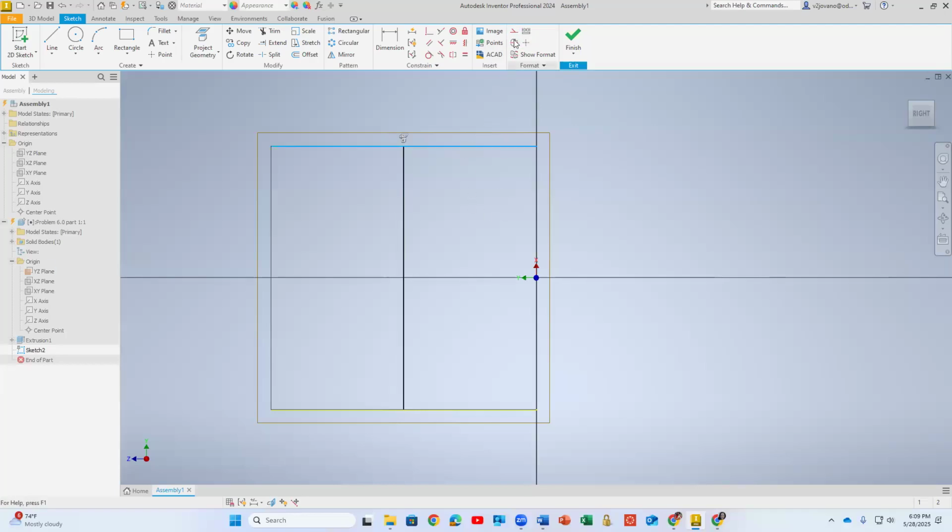Okay, and I want to try switching this to construction and the other to construction, because they just help me to build the line. And they want me to make a circle here, so diameter 0.5. Okay, I don't need this anymore, so I can switch this one to construction. All you do is select the line and then click on the construction. So now it's kind of invisible.